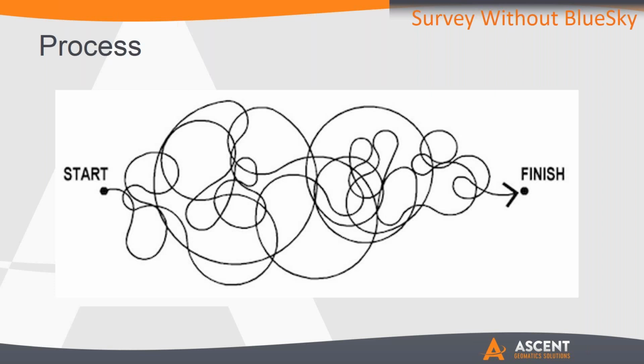It's a lot of chaos, and that can definitely happen in your business process if you do not have a good quality assurance and survey validation process in place. Typically, and from a conventional point of view, we have survey crews that go out, and those could be multiple crews. It could be single crews. Then what happens is, as the data is being collected, it could be nightly, daily, weekly, depending on what your process is for importing that data into AutoCAD, CSV, spreadsheet, TBC, whatever the process is that you're using.